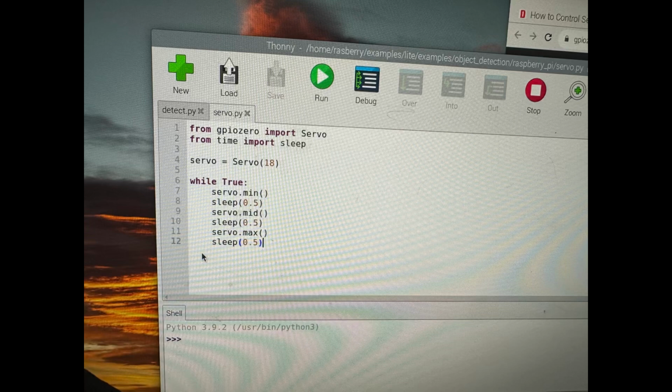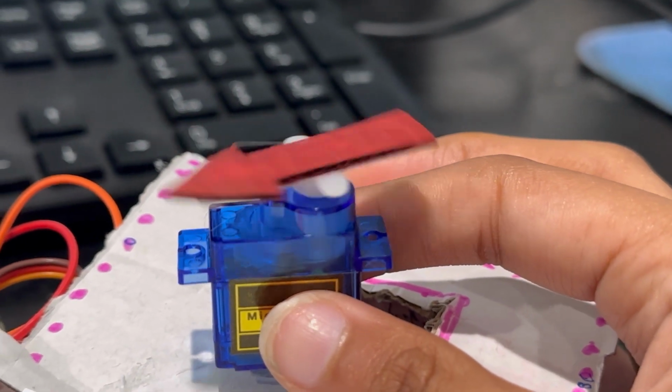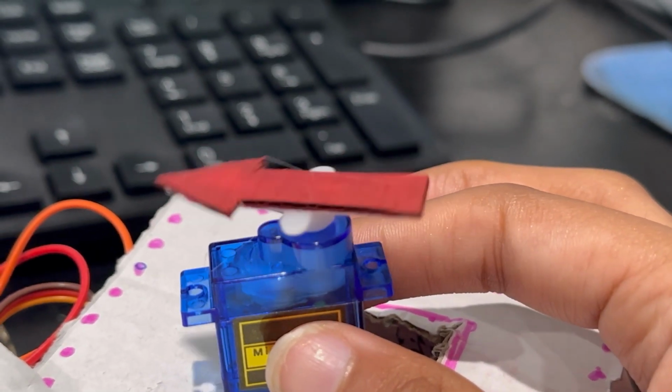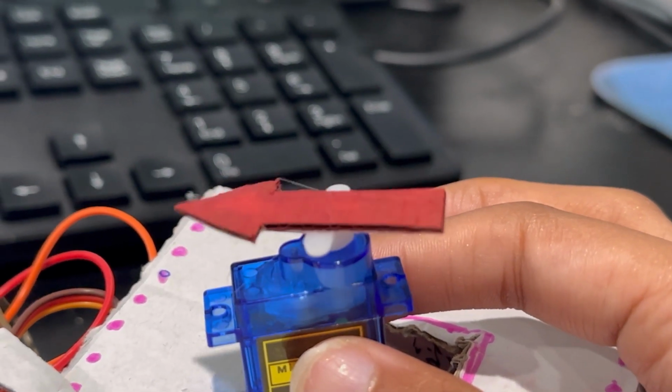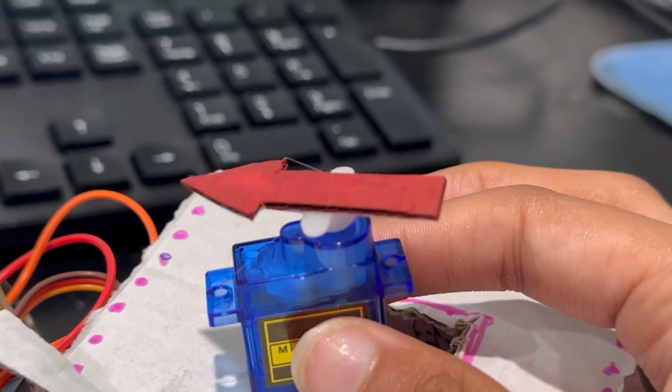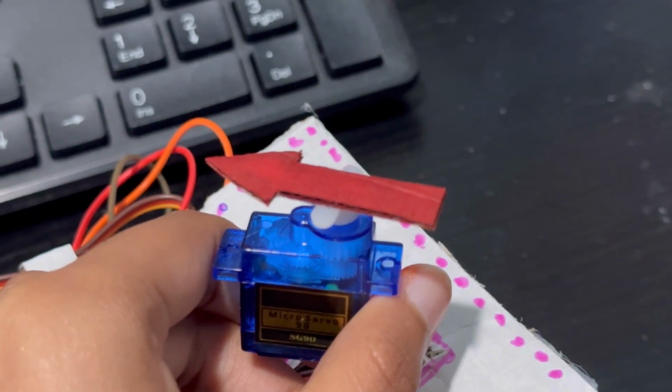The next step was connecting the servo to the program. If the program detects the desired object, the servo will move to a certain degree. I initially used a more basic method of controlling the servo, programming it to move to the minimum, middle, and maximum values it could turn to. However, when I attempted to integrate this into detect.py, there was excessive servo jitter. I learned that changing the pin factory was a solution to this and attempted different versions to find which worked best. This seemed to be pigpio. However, there was still significant servo jitter. To fix this, rather than specifying degrees, I used pulses. After setting it using the terminal, the code was successful.